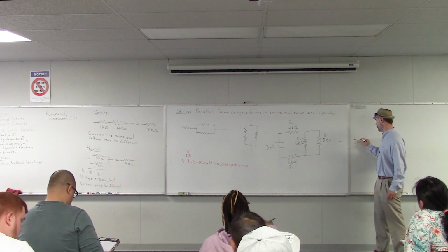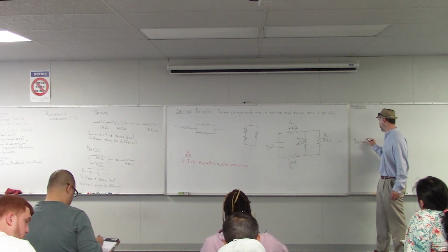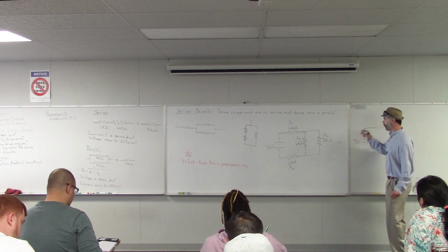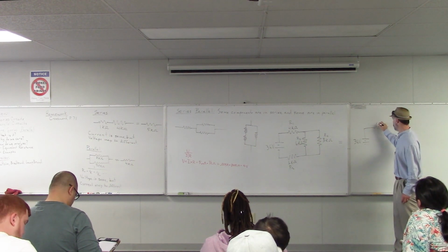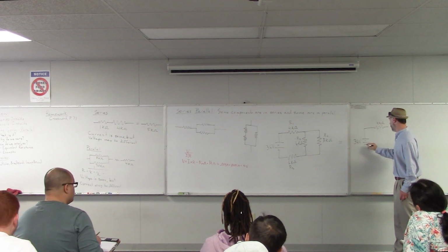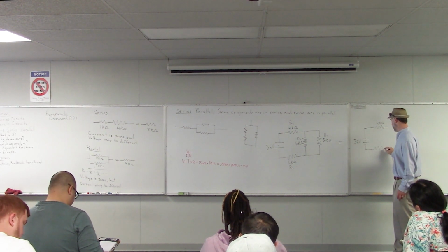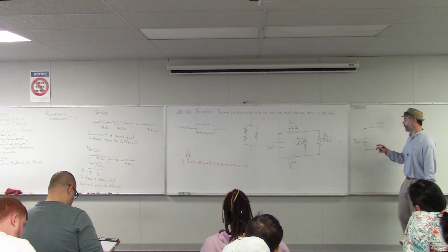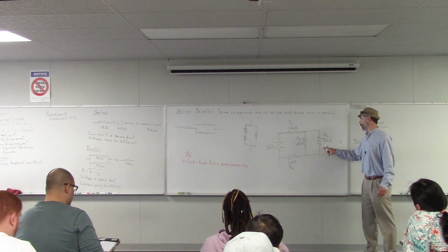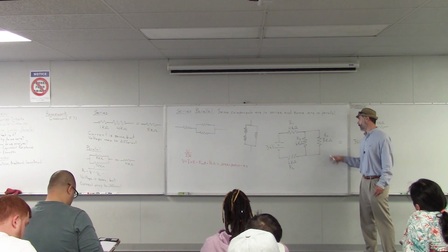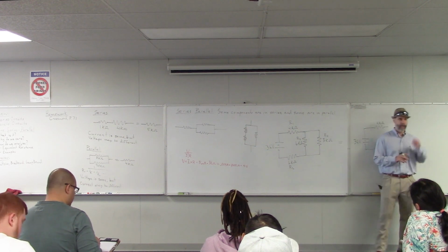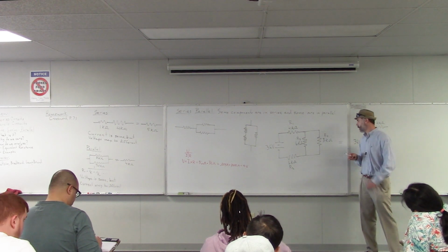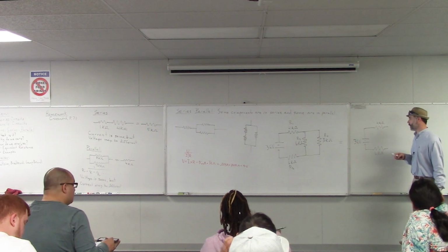So we've got 36 volts here, and we'll keep the other resistors the same. This will still be 4 kilo ohms, and down here we'll still have 6 kilo ohms. But now we want to find the equivalent resistance for these two. Can we just take one of their values and divide by 2 resistors? No, because they're different values. That formula would only work if they were the same. So we have to use the equivalent resistance formula.